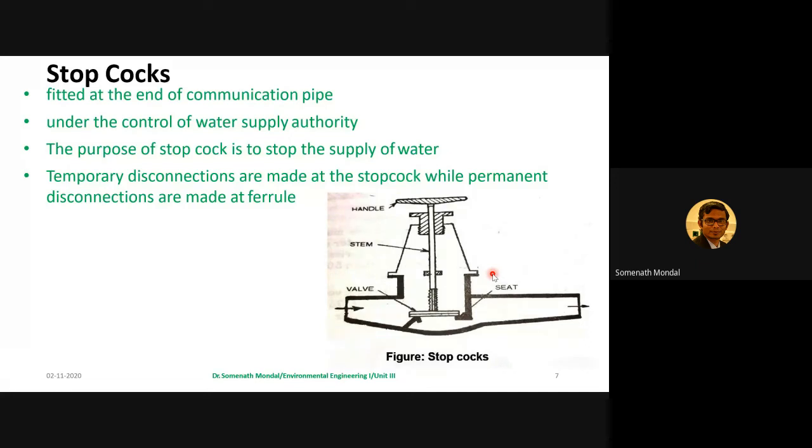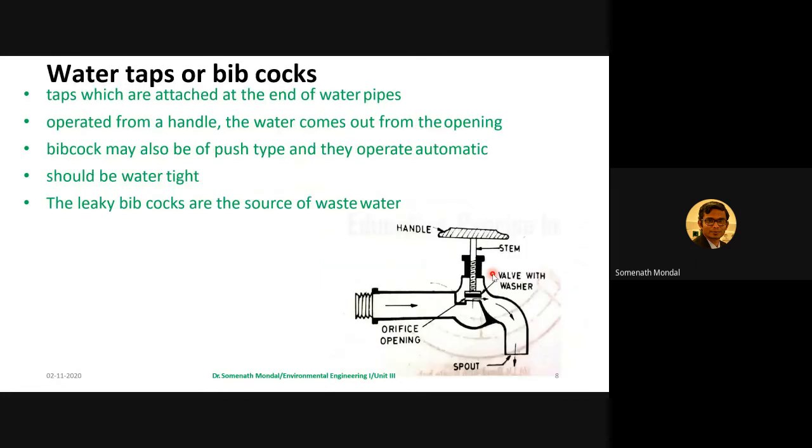But once you raise the handle, the valve will go up, it will get detached from the seat, and then the water will pass and go into the water meter. Fine. And mostly they are extensively used in pipelines up to size 50 mm. So this is the way we basically utilize stopcocks in creating more flexibility in the main water supply system.